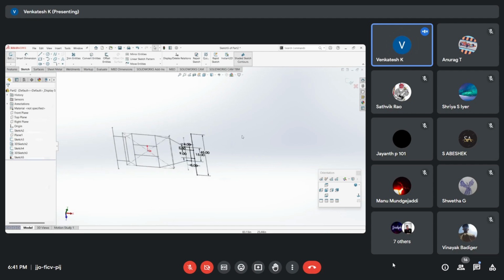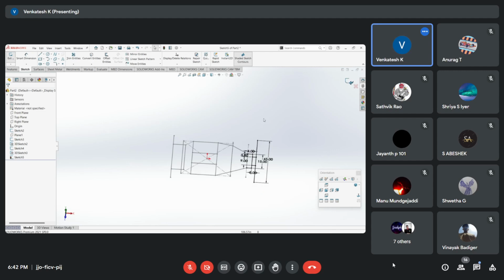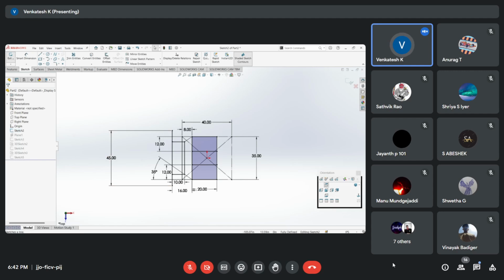This is the front. This is the bottom part of the chassis. The last part of the chassis will be the firewall, and also the side bumpers. We'll do it in two separate parts again. We can do the side bumper part in the first design of the chassis itself. We'll go to the first one, edit sketch. You just click on it, you get an option of edit sketch.